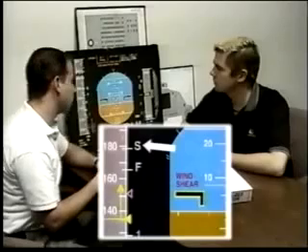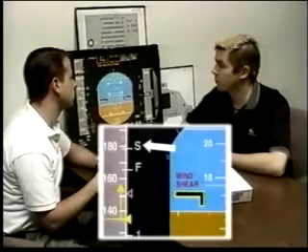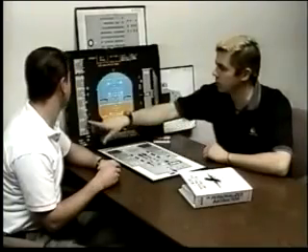We have S speed. What does S speed indicate? According to the UAL flight manual, that's called minimum slat retraction speed. During takeoff phase, when we reach S speed and are accelerating through it, we can retract our flaps from position 1 up. But it's also used during the approach phase of flight. If I've activated the approach phase of flight and I'm in all autoflight, then the aircraft will slow and maintain S speed. The thing to remember is that's an optimum speed to be flying, not the minimum. The minimum speed is VLS.